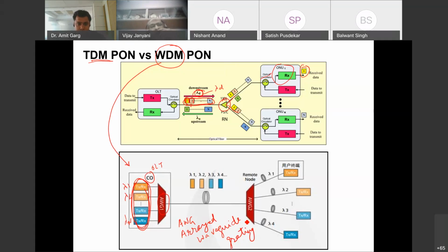So this device is actually acting as a multiplexer, and as a demultiplexer on the receiver side. When you have a number of wavelengths, called n wavelengths, and these are multiplexed, all these wavelengths are now mixed together in time. In the time domain they are mixed, but in the frequency or wavelength domain they are all separate entities. So they all pass together through this fiber, and when they reach the receiver, they are demultiplexed by using another AWG, which is marked as AWG2 here, AWG1 here.